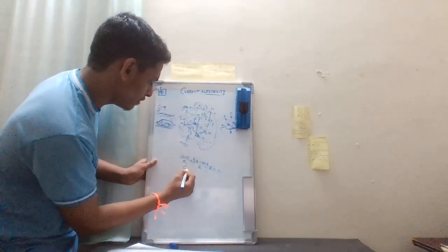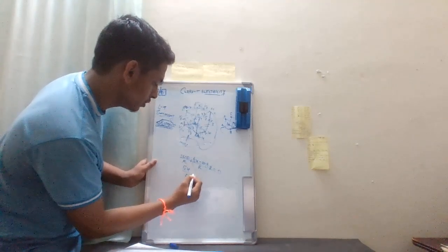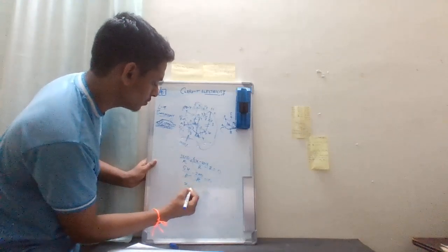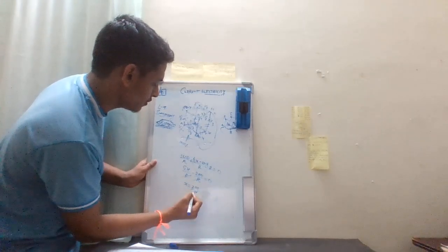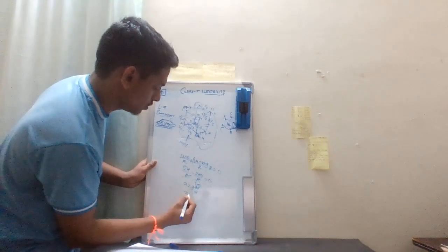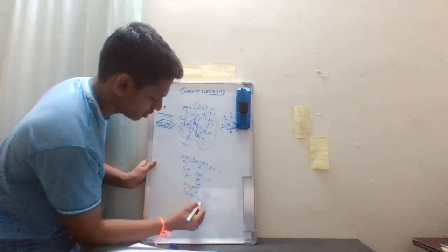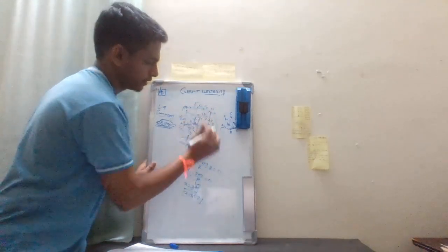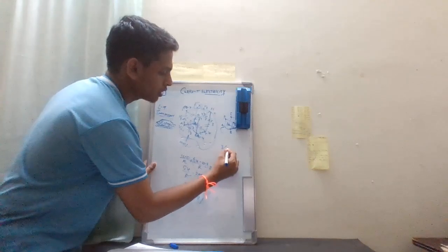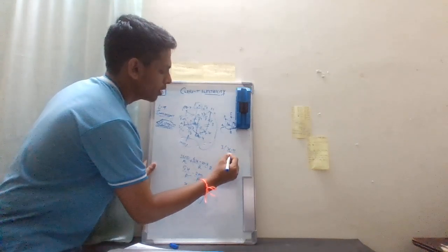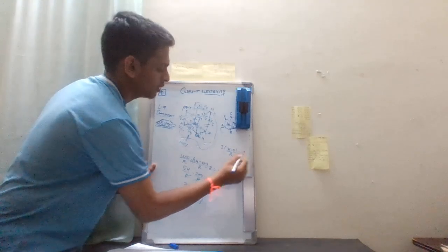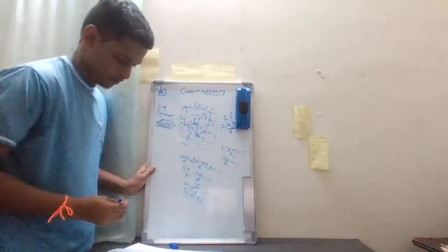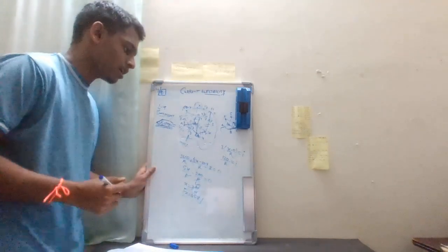This would be 5X by R minus 200 by R equal to 0. R now cancels. X equals 200 by 5. 5 4s are 20, 40. So X equals 40 volts. Now we'll apply here. So X, X, X. So 3 times X minus 0 by R equals I. So 40 gives 120 by R equals I. So I equals 120 by R.